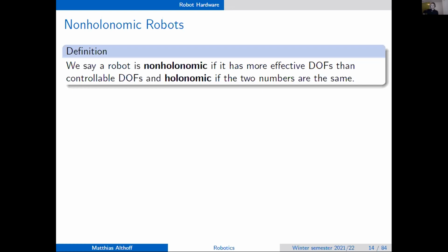Yeah, somebody wrote X, Y. So we have 2, which is the steering. That's 1 degree of freedom, and we have acceleration. Braking and acceleration are the same, it's just a different sign. One is positive, one is negative, but it counts as 1 degree of freedom. So we have just 2 degrees of freedom that we can influence, but the system has 3 degrees of freedom. That means it's non-holonomic.